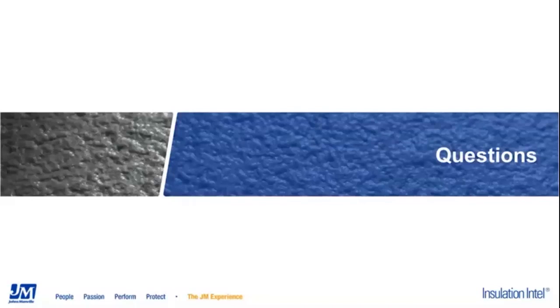All right. The next question is, Wyatt mentioned using heaters for the substrate in cold temps. Are certain heaters better than others? So, yeah, I think that just goes back to that prior conversation. So something that puts out a nice dry heat, either natural gas or something like the salamander heater that puts out a good dry heat. Electric heat would certainly be fine, just don't know how feasible that is.